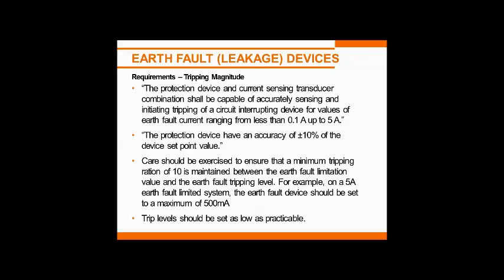In this case, the accuracy of our measurements has to be plus or minus 10%, and this is where the standard has changed. Previously, very early, it just had to be less than the set current, so it could be anywhere. Then it had to be within 20% of the set current, and now we have plus or minus 10%. And where they have tightened up, of course, is in the time, so that while the current is plus or minus 10%, the time is certainly a narrower requirement these days.